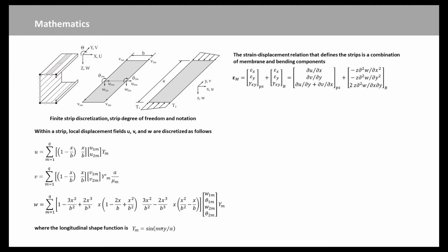The strain-displacement relation that defines the strips is a combination of a plane stress condition for the membrane degrees of freedom U and V, and a Kirchhoff thin plate theory for the bending degree of freedom W.